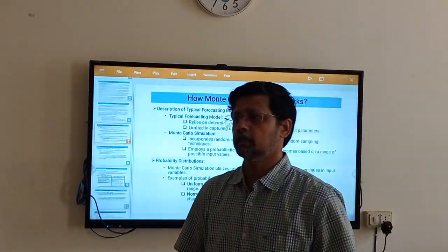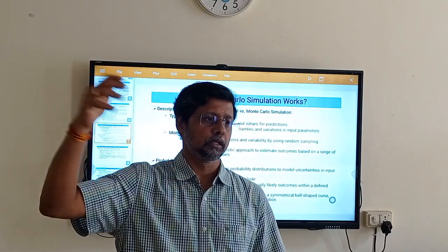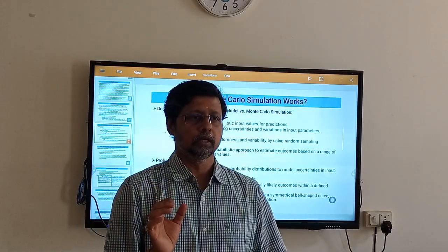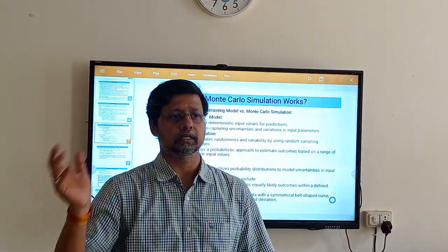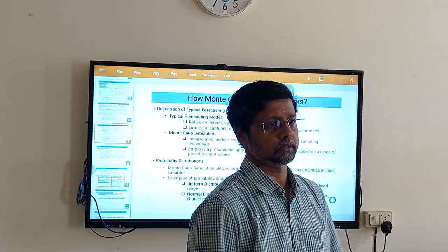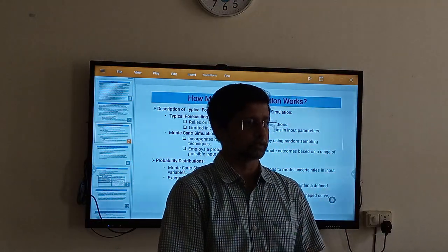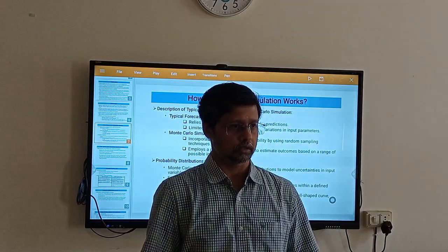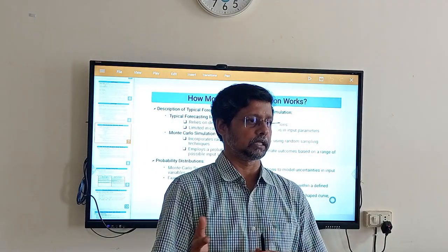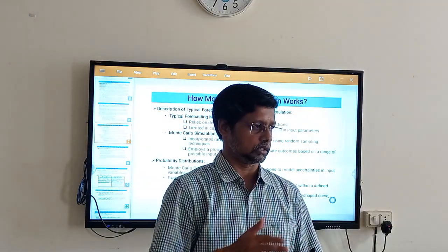You know how the characteristic works out from the origin to the saturation point. Then we are able to identify which region of the entire characteristic I can use as a cutoff. Even if the device is not in cutoff, meaning the supply is not absolute zero, I can treat it as a cutoff. Which region I can use as my linear region, the active mode, whatever you call it. Most applications will work in that area.